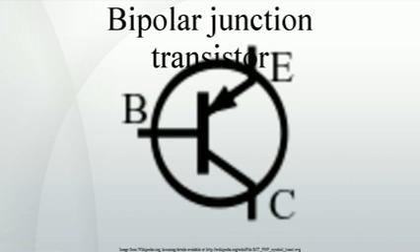In this on state, current flows between the collector and emitter of the transistor. Most of the current is carried by electrons moving from emitter to collector as minority carriers in the p-type base region. To allow for greater current and faster operation, most bipolar transistors used today are NPN because electron mobility is higher than hole mobility. A mnemonic device for the NPN transistor symbol is "not pointing in", based on the arrows in the symbol and the letters in the name.